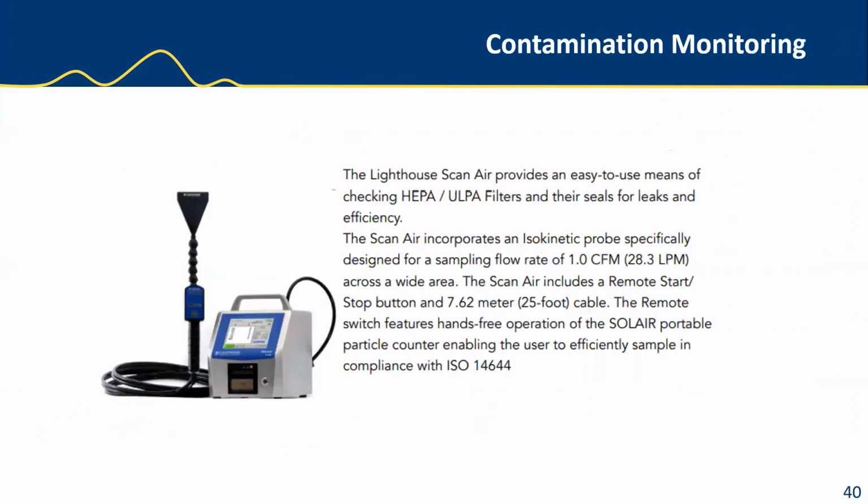Finally, for applications where HEPA and ULPA filters need to be validated, the ScanAir Pro is a valuable piece of equipment and needed in every facility. Air filter integrity is crucial for the cleanroom operations and for control of contamination inside the cleanroom. ISO 14644 Part 3 allows for the use of airborne particle counters to conduct filter validation activities and verify filter integrity. This method uses reference particles instead of oils.